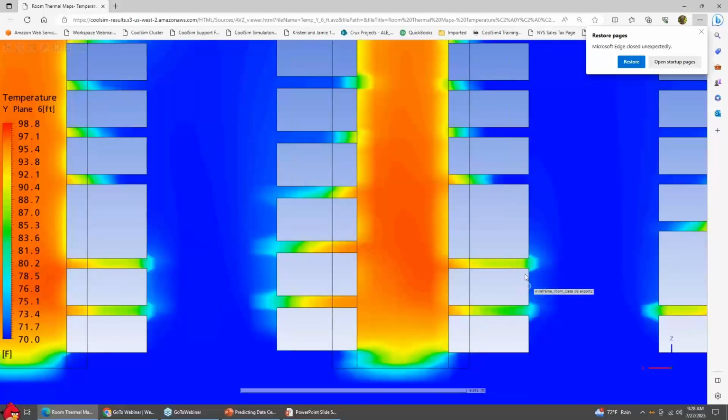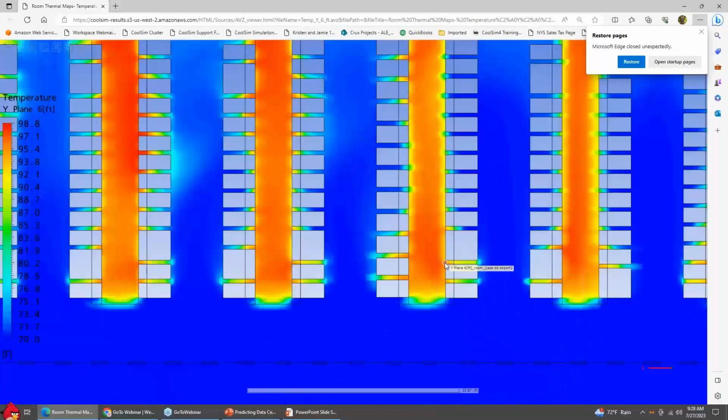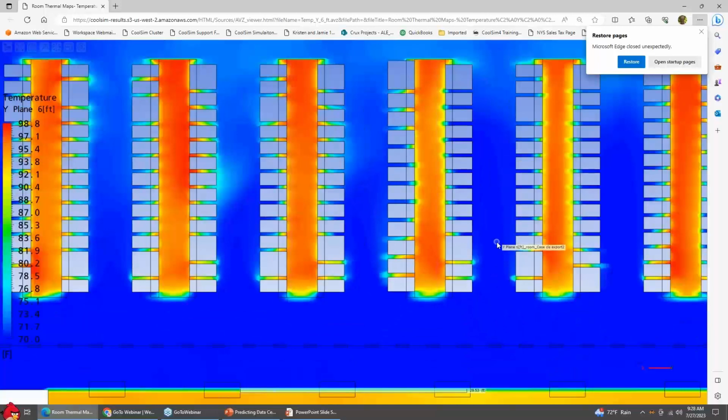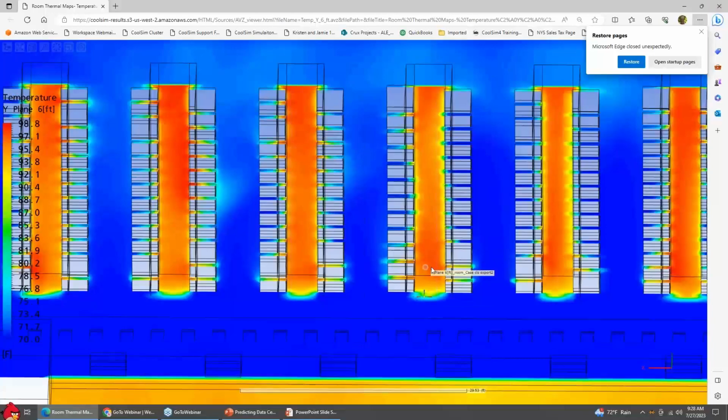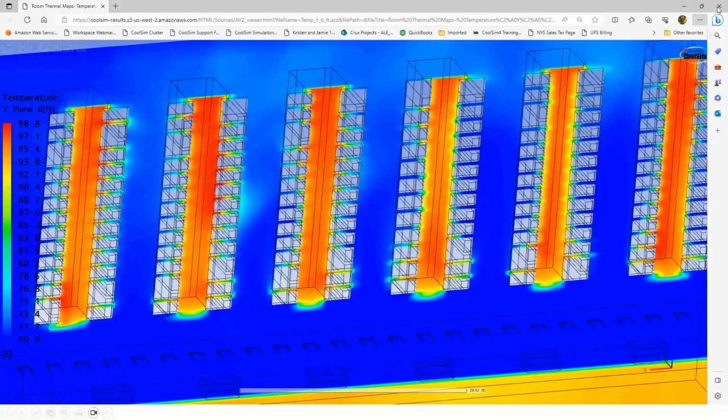This is inside the rack. There's not much you can do about it. It's going to come pushing through. It also, by the way, is the same issue when you have it between racks. So this is containment, and these seals along this edge right here are not perfect. This is why you need a positive pressure gradient from the room itself into the contained area. So I thought I'd just show you that. I've showed you that before. It's a good representation of what's going on in the room and works a lot better than just an image like this, okay?